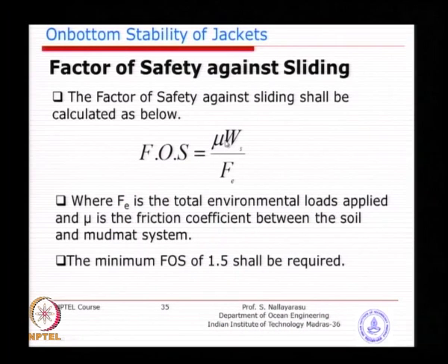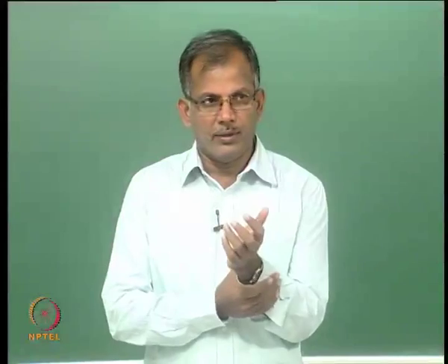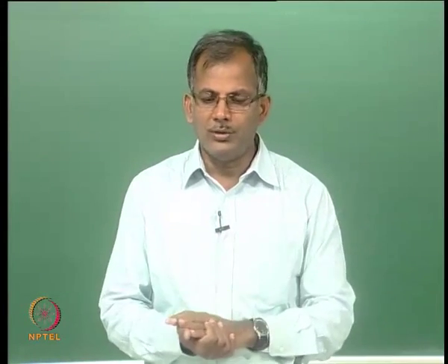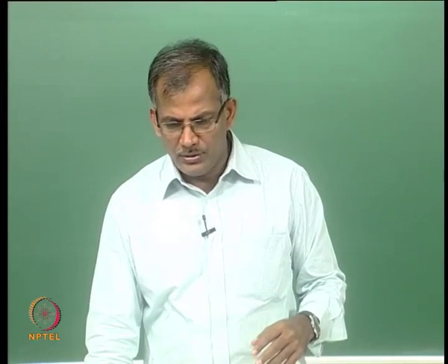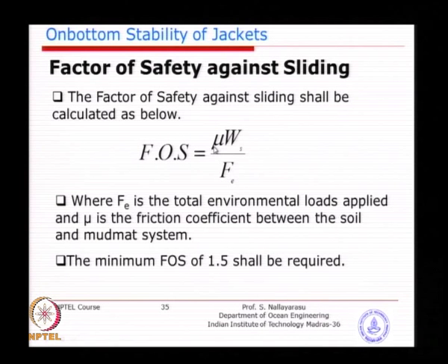So basically you can see this particular formula or methodology does not relate to the mud mat area. You can see the weight plays a major role, and the friction factor is independent of the surface area of the foundation. If you have a larger or smaller one, it does not matter. Mu is not really a surface area parameter, and does not account for the larger or smaller extent of the mud mat.